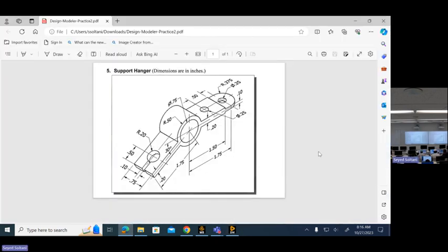Let's go back to the drawing. Next, I'm going to build this part. The way that I'm going to build this, I'm going to use a rectangle that extends from this edge, which is my y-axis, all the way to this edge with a total length of 1.5 inches.